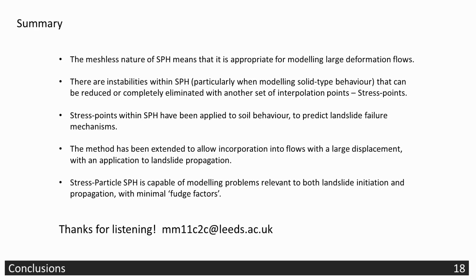And does this new method introduce problems for boundary conditions in SPH? Yeah, it does actually, but there's a way to kind of switch off the points. So near the boundaries, you can just have standard SPH, and then you can use the stress points away from the boundaries. You can use them near the boundaries, but it does cause some problems, yeah.